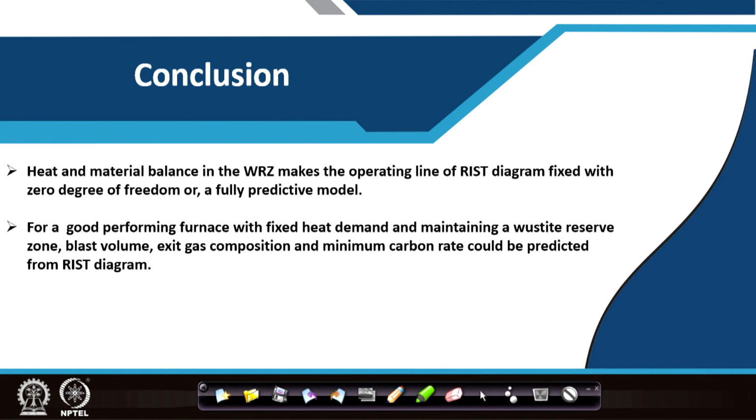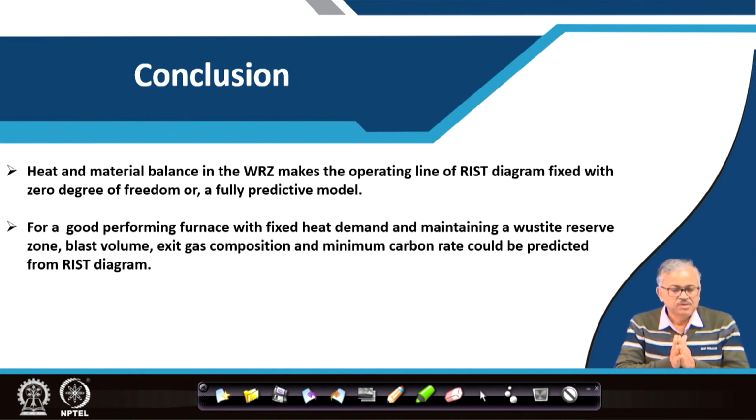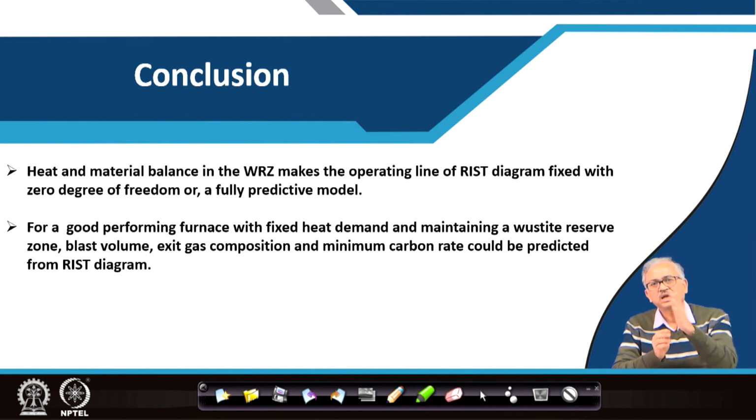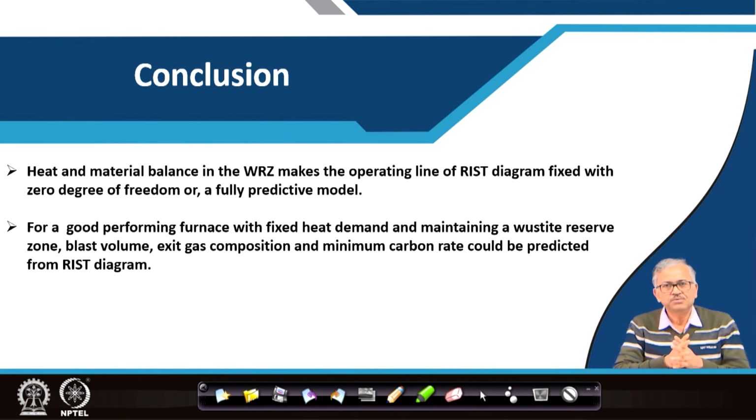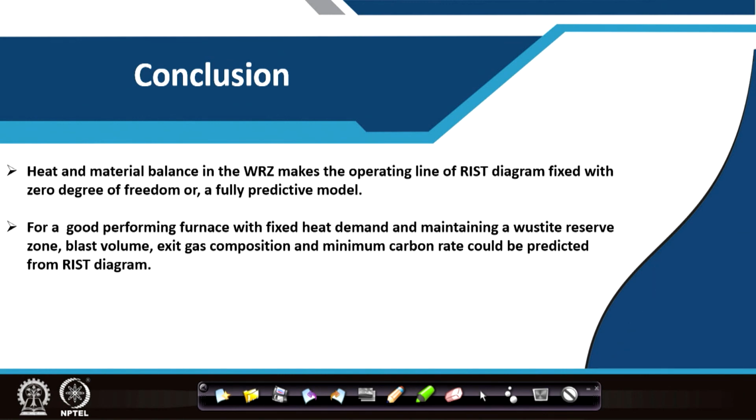So we can have the minimum or optimum coke rate, but the furnace can operate along the fulcrum of the thermal pinch point, though it can be less efficient. If the line moves to the left hand side, it is less efficient. On the right hand side, the line cannot move, because then you will not satisfy the equilibrium requirement of the FeO-Fe system. So this is all.